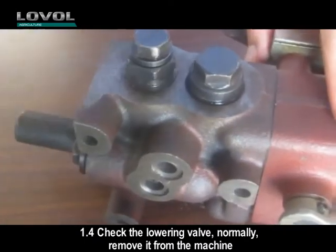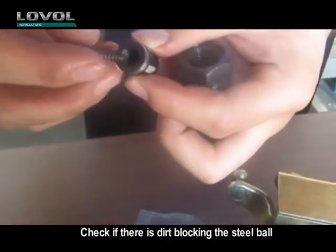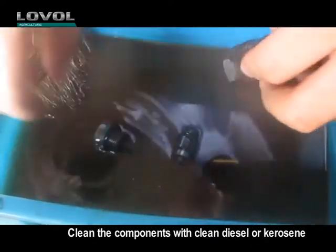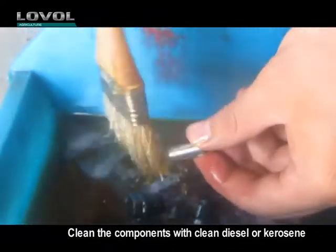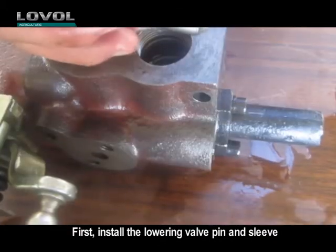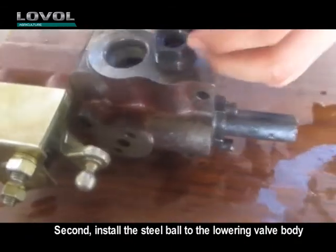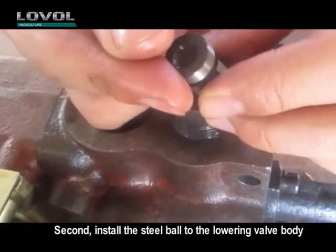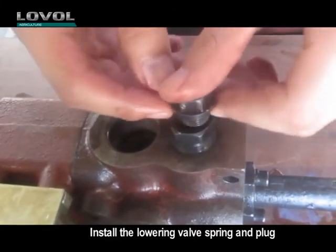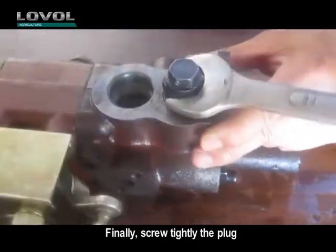1.4 Check the lowering valve. Normally, remove it from the machine. Check if there is dirt blocking the steel ball. Clean the components with clean diesel or kerosene. Place them in order so that you can install them in order. First, install the lowering valve pin and sleeve. Second, install the steel ball to the lowering valve body. Install the lowering valve spring and plug. Finally, screw tightly the plug.